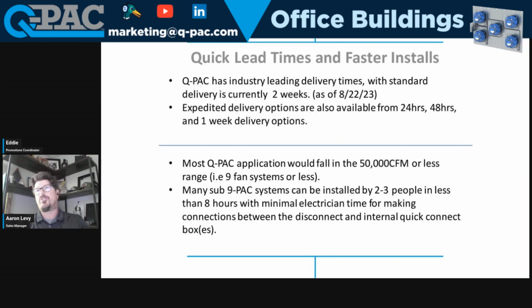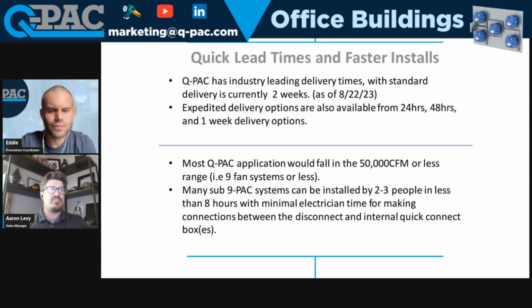A lot of questions people ask about EC fans is what their lifespans are. They have SKF bearings. Their L10s are typically between 50 and 80,000 hours. So they'll have about 10% field failure rates somewhere between 5.5 and 10 years. Their mean time between failure is somewhere around 100,000+ hours.